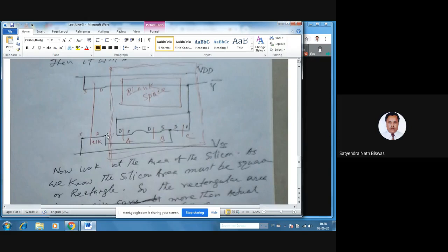That's why what we need to do, we need to arrange these A, B, C transistors in a vertical way, right? Instead of this x-axis, we have to put it in the y-axis, just like yesterday we did in the y-axis, and then we can save. Look at those diagrams from yesterday. It was a little amount of area here, like this kind of rectangle. Here I am showing by mouse, right? This was like this much, but if you use this kind of diagram, lots of space will remain blank in the integrated circuits.